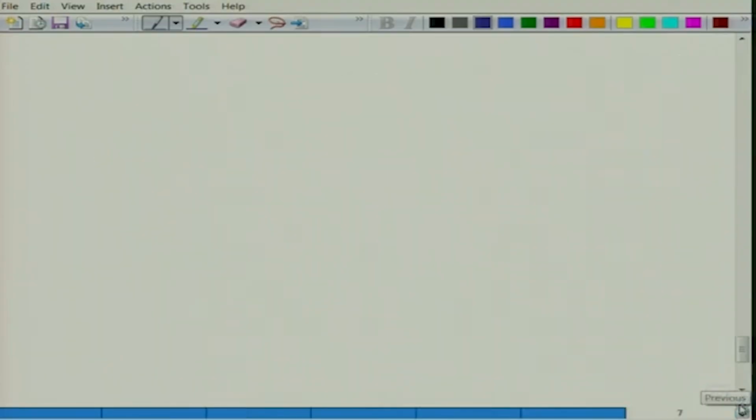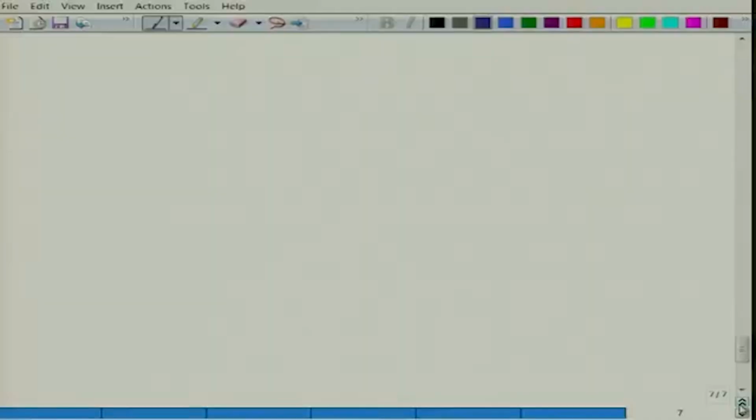Now, the next thing is to look at, so what we have looked at until now is the stoichiometric defects which do not change the stoichiometry of the oxide, like Frenkel defect, Schottky defects, and then we looked at the cases of non-stoichiometric oxides where you have oxygen vacancy, you have oxygen excess or metal excess, or oxygen deficiency or metal deficiency, and depending upon ionic or electronic compensation you will form appropriate defects.